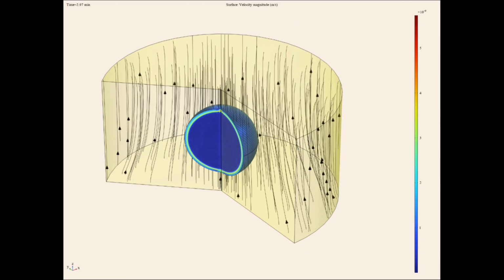This animation shows the output of our CFD simulation, where you can see the gas profile inside the pellet. The key point is that hematite has low porosity, and as the reaction progresses, the porosity increases. Therefore, the hematite to magnetite reaction initially proceeds in a linear manner. Because of this, we could even use unreacted shrinking core models at this stage.